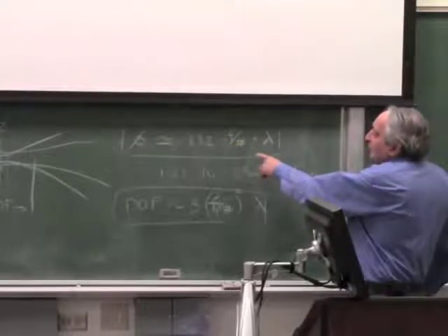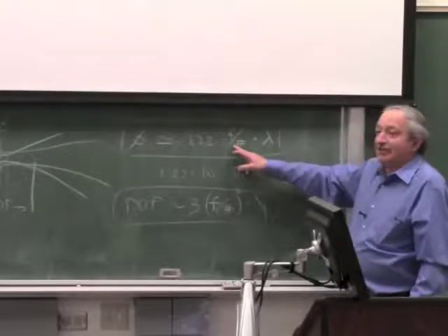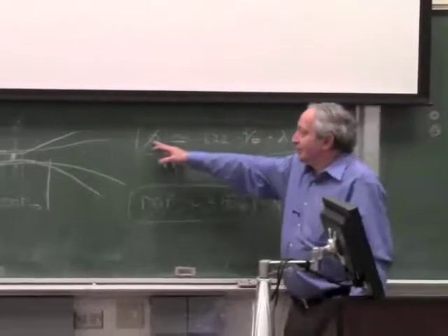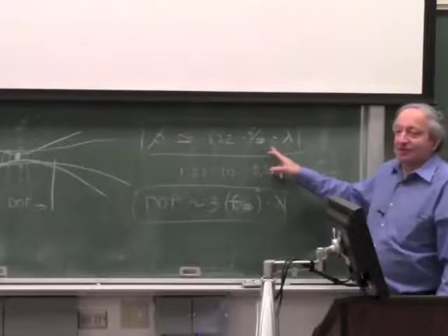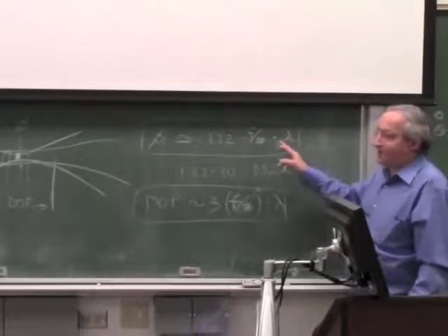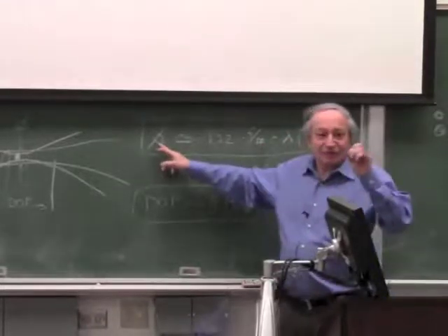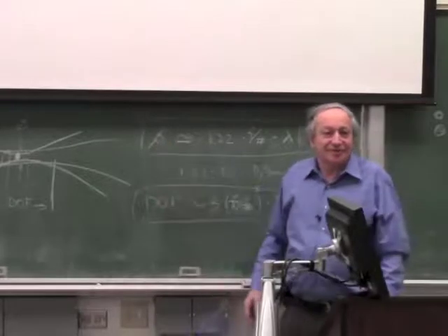So if you look at this formula, this f number has to be about 1. So the resolution will be 1 micron, because that's about 0.5 times this 0.6. So this has to be around 1. Otherwise, you don't get a diameter of resolution spot of 1 micron. Okay?